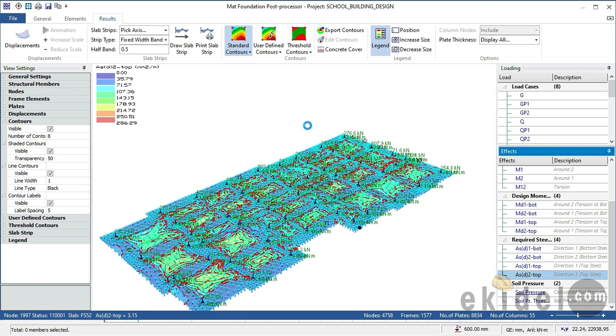This stage alone takes a lot of time. This soil pressure, you can see how all these ones we are just loading one by one. It didn't take much time, but this soil pressure can take you up to 30 minutes. And if your system is not that strong, or your system RAM is about to be filled up, then you have to wait sometimes 2 hours, 3 hours. And if the building is very, very massive also, this stage alone will take you longer. As you can see, this building is already 35 meters by 25 meters. So this building alone is a big building. So that's why you are seeing it taking time. But we will just hold on for it to load up.